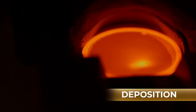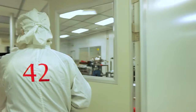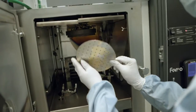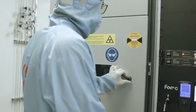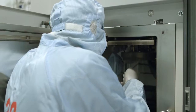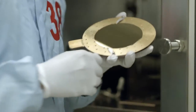The wafer with a patterned photoresist now travels to the metal deposition bay, where it is loaded in a physical vapor deposition unit. Metal is vaporized and it coats the entire surface of the patterned wafer, both those covered with photoresist and the exposed wafer areas.